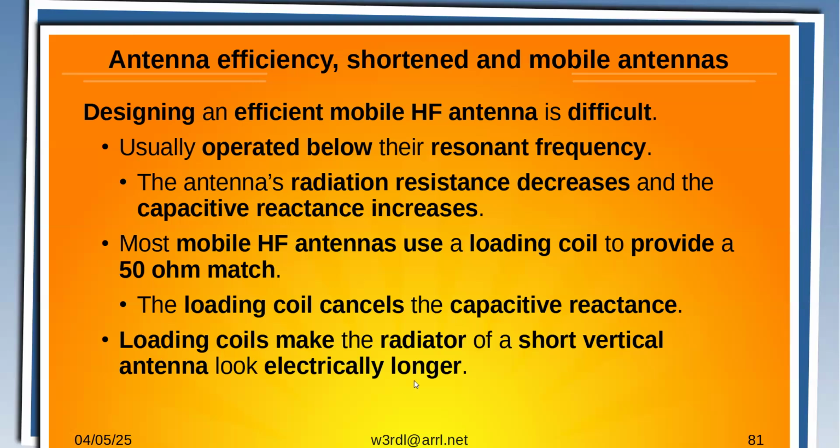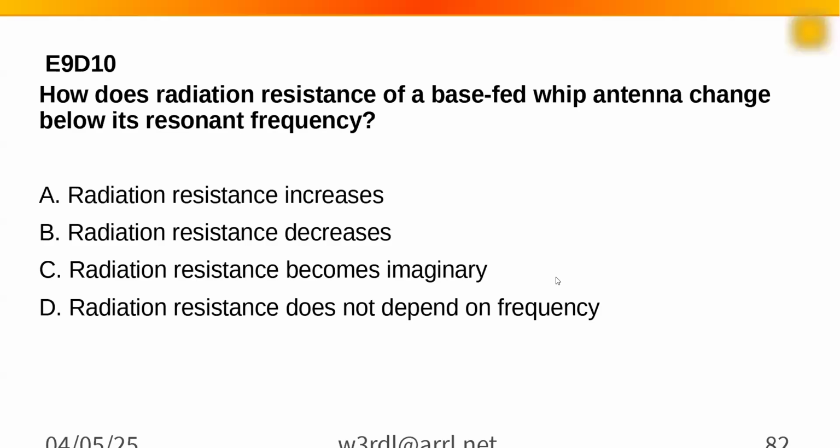They say it makes it look electrically longer, but all you're doing is canceling out the reactance. So you're going to make it resonant at that particular point.